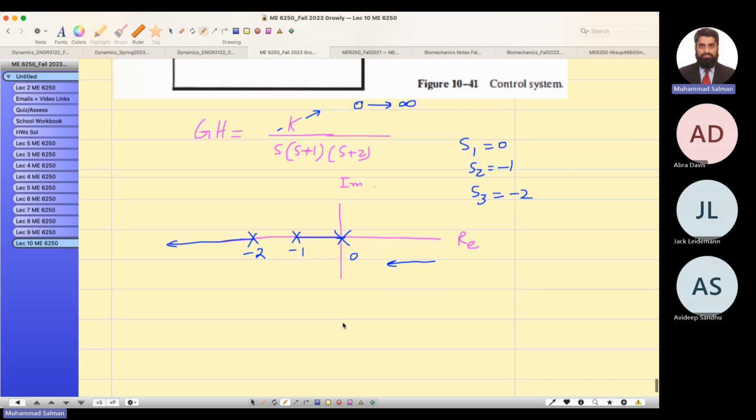So as you can see, at this pole the gain over here is 0. The gain over here is infinity. You see my point? So at infinity, the pole goes and meets with the zeros. And the idea of root locus is that at any instant, you should see the track, and they should not go to the right half plane.